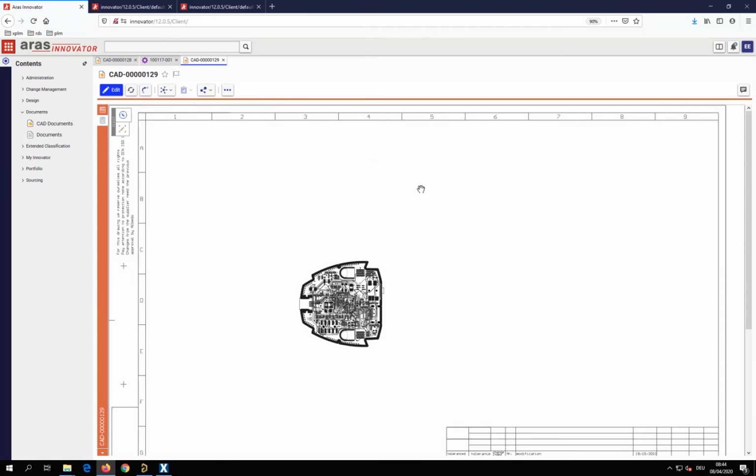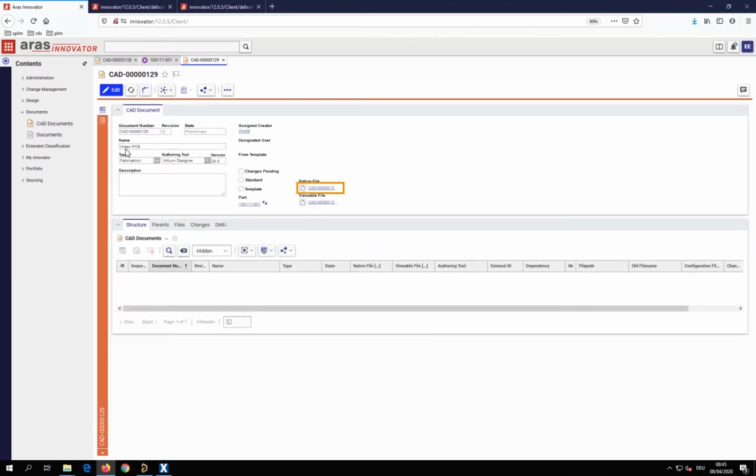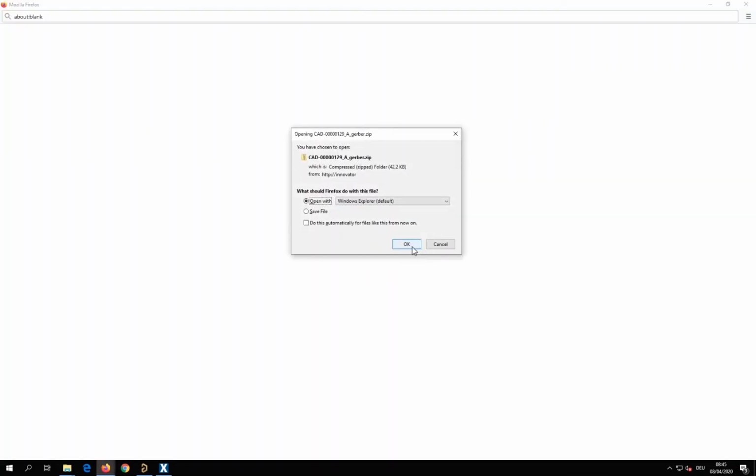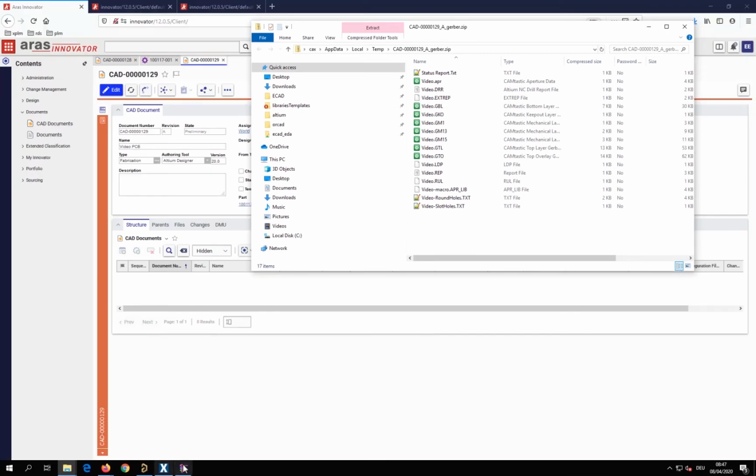This viewer shows the PDF containing a drawing of the unassembled board. All placeholder parameters in the title frame are replaced with PLM parameters. Shown next are the zipped Gerber files for the manufacturing of the bare board. The Gerber data can be visualized in this dedicated viewer.